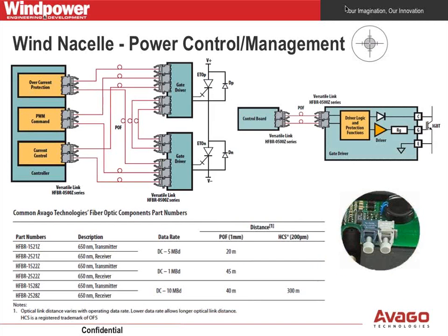This just gives you another pictorial of the products that might be used for these applications. In the lower left-hand corner, these are the products that were developed in the mid-'80s by Hewlett-Packard. They are called Versatile Link, as you can see in the pictures above. They offer control and communication from DC data rates, so very low. You can have very static signals for a long period of time, which is important for a lot of these low-speed control and low-speed feedback signals, up to about 1 megabaud, 5 megabaud, 10 megabaud, and we'll see that we have a 50 megabaud device coming out soon.